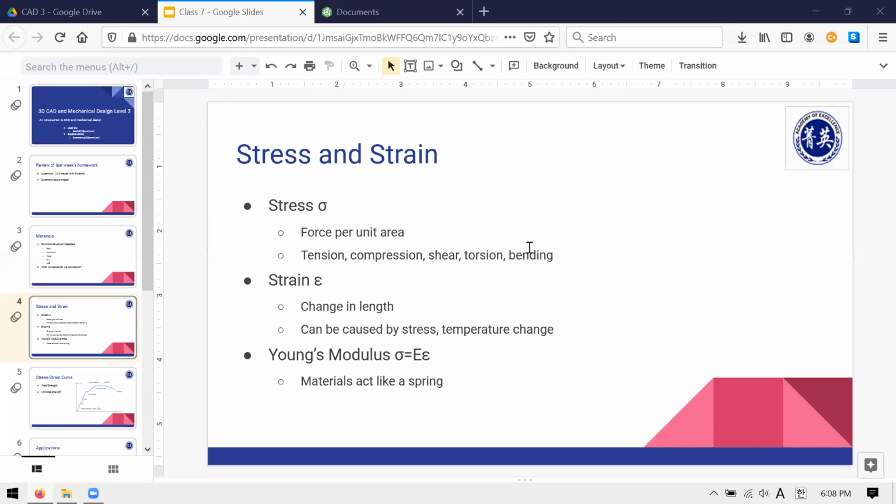And opposite of that is compression, where you're trying to push things together or into itself. And so you may have heard things like cables are really good at tension, concrete is really good in compression. And so those are material properties that can inform how you design things and what you eventually make the thing that you design out of.